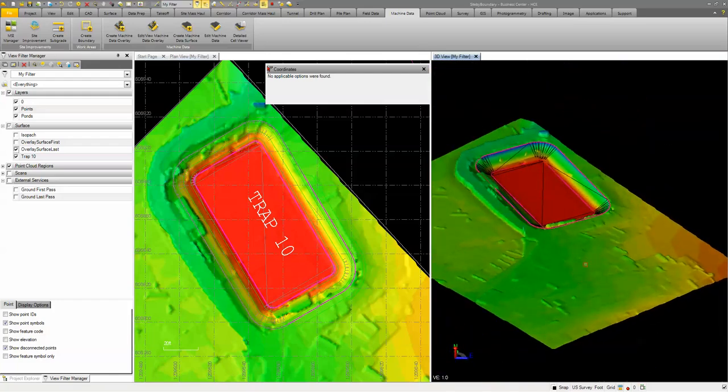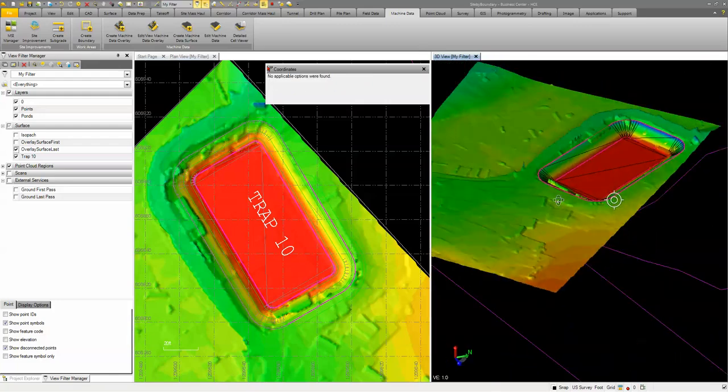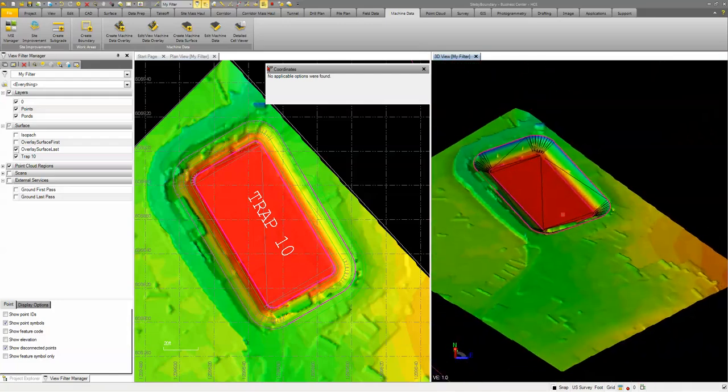Okay, so you can see they're still moving material out on site. So again, this is kind of a work in progress. If I put my cursor over here, you can see now as I look at that last pass, I'm at 447, 446. And even visually, I can see that, hey, it looks like we're pretty well right on target.